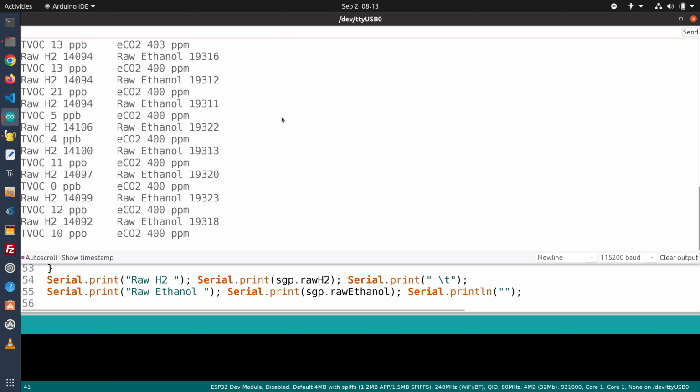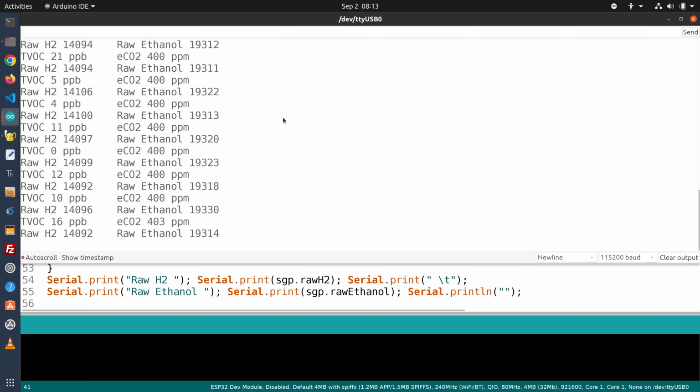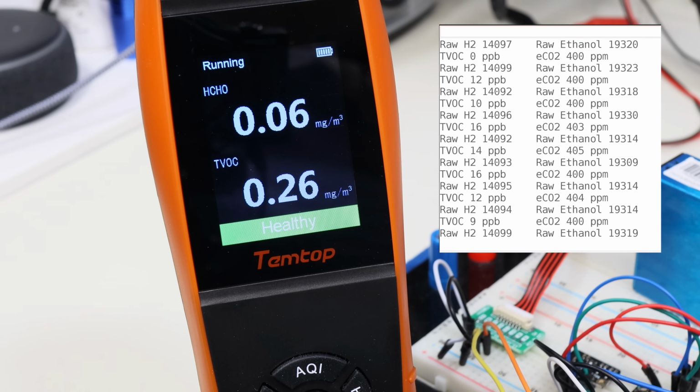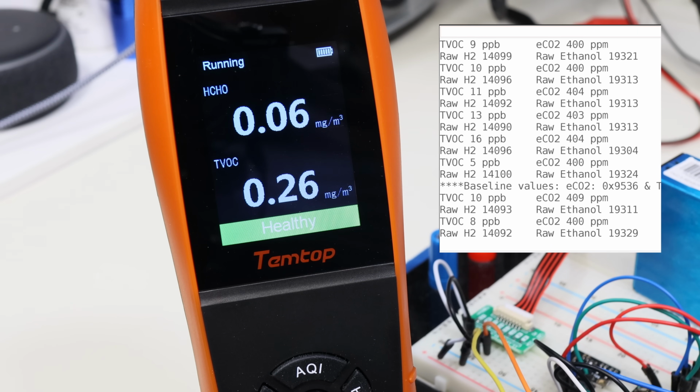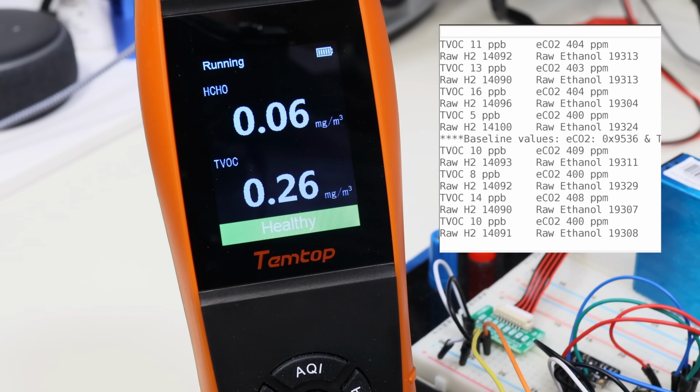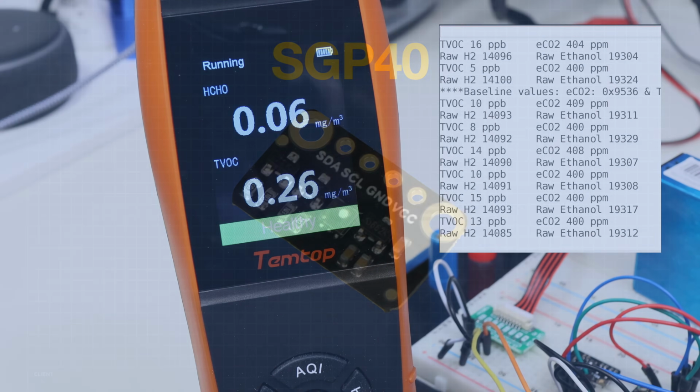You can also see that it gives some other readings in addition to the TVOC and the CO2. Now once again, the unit over here is parts per billion, so I'm not sure how this compares to my commercial one, which is reading the total volatile chemicals down over here using a different unit, but it does seem like a very easy unit to work with, and it brings you back a lot of parameters about the quality of your air.